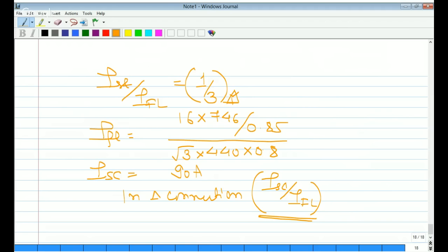What is the question that Divya has asked? In the open circuit, short circuit question, if I have an instrument that can be connected on the LV side in the SC test, actually you can then conduct a short circuit test on any other side also. It is not any problem for us. That is your choice because losses will remain the same no matter which side you conduct the test. So heating will not be an issue. It is your choice, so that is not any problem.